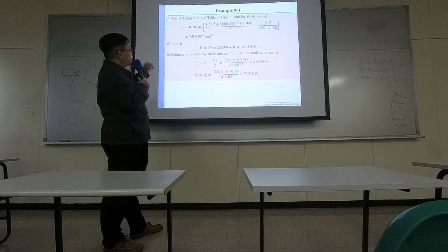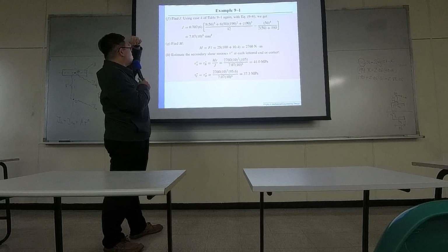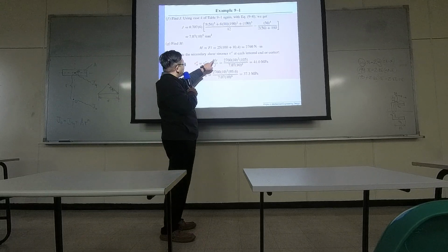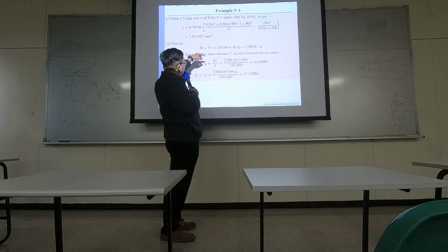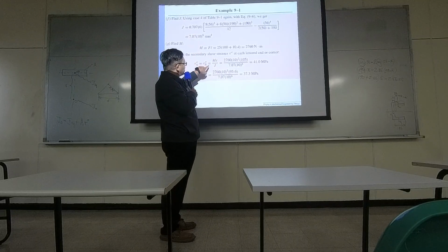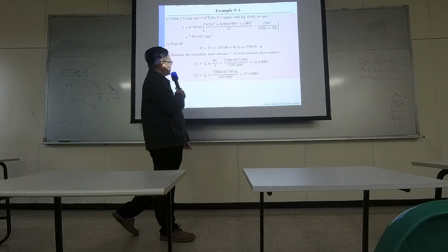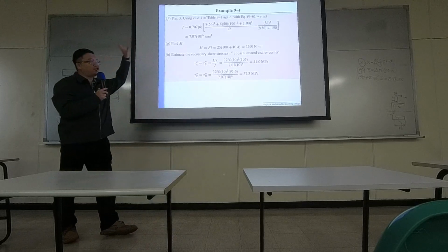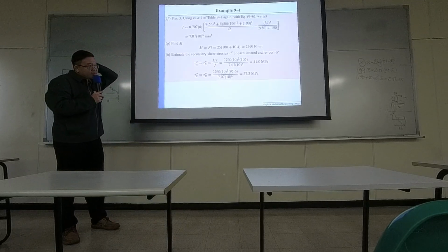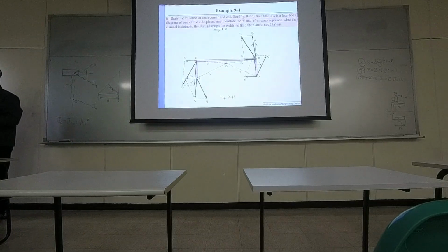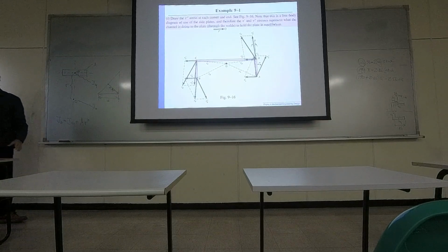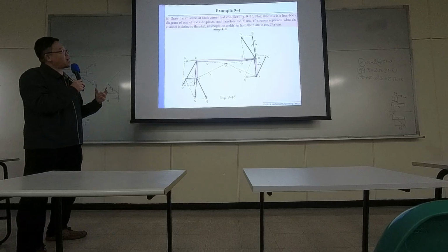So the shear at the corners will be computed by moment times the radius, which was computed at different corners, and divided by the common J. The Js are the same. So once it's done, you can make drawings like this. So the overall effect is like this.